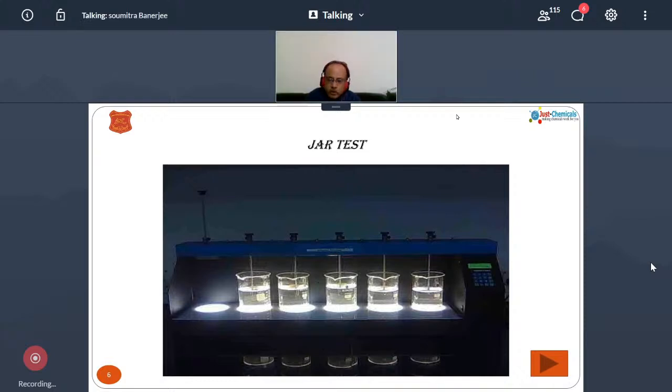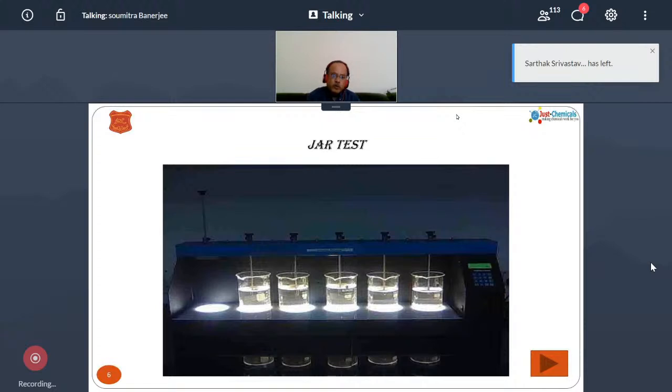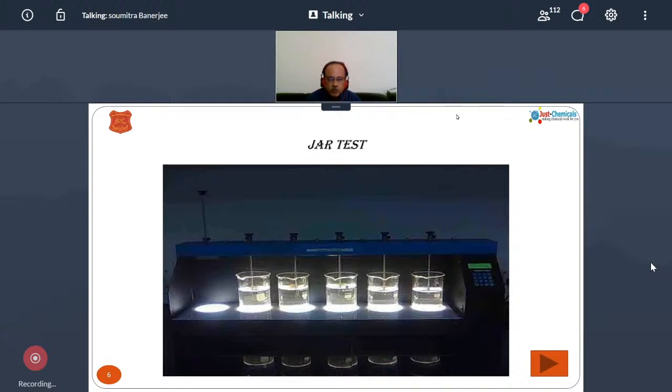Now, as you saw in the video, the process is quite tedious, and we need to be very sure about addition of coagulant and flocculant in the system, because overdosing will create a carryover of either aluminium or iron. Aluminium will go into the reverse osmosis membranes and do an irreversible scaling in the reverse osmosis membrane, which cannot be removed by any method, and it can also form aluminum silicate in the condensers and heat exchangers.